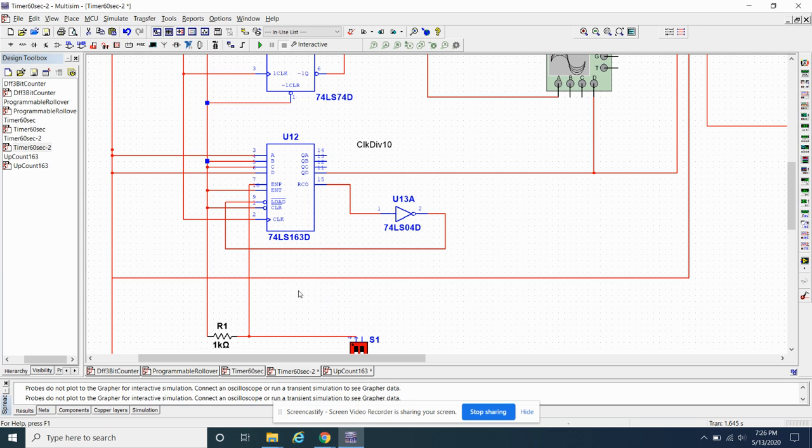Okay, if I want to pause this, really all I want to do is stop the divide by 10 clock. I just want to stop that divide by 10 clock based on a switch. If I stop the clock, then everything is going to stop, right? All my other dividers are going to stop. And I haven't looked at how I'm generating the second counter yet. This is just simply for the divider, right? This is just doing the divide by 10 of the master clock.